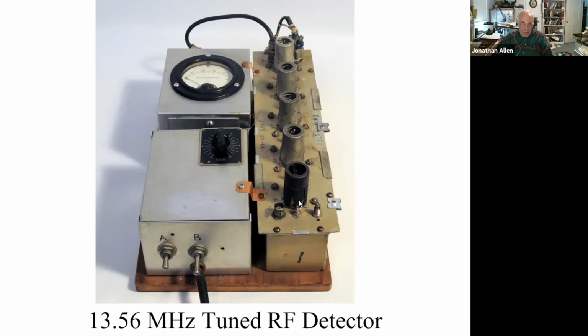And when you crank up the gain, it has a sensitivity of microvolts and a gain of a half million between the input and the output. And these shields on the tubes are necessary because if you take them off, just the capacitive coupling between the input tube and the output tube will cause this thing to break into oscillation.